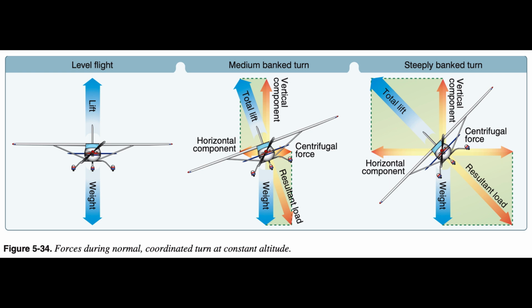Newton's first law of motion, the law of inertia, states that an object at rest or moving in a straight line remains at rest or continues to move in a straight line until acted on by some other force. An aircraft, like any moving object, requires a sideward force to make it turn. In a normal turn, this force is supplied by banking the aircraft so that lift is exerted inward, as well as upward.